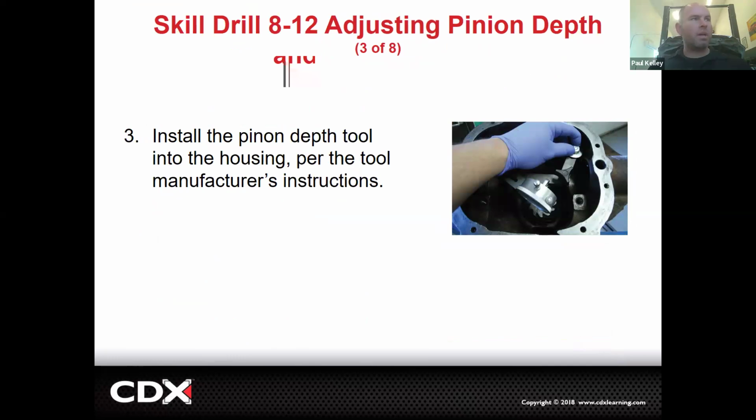And this is that tool I was telling you about. You can't see it well, but this is a rig. It bolts up to the case. It goes over here. You're going to set it up the way service info says, and then it's actually going to have a dial indicator, and it's literally going to measure the depth of the pinion. And there will be a procedure, there will be a specification for that depth. So if this tool measures the depth and it's too shallow, you would reshim it right there. And if it's too deep, you'd reshim it. You could set your pinion depth using this pinion depth setup jig. Okay. Toyota doesn't list that. Toyota doesn't show any of that stuff.